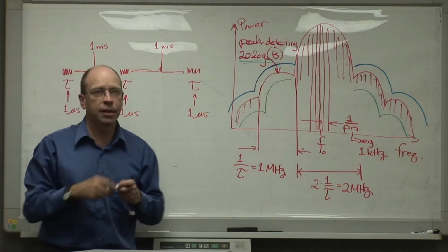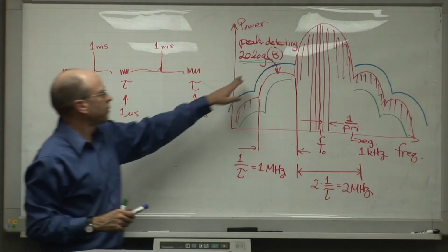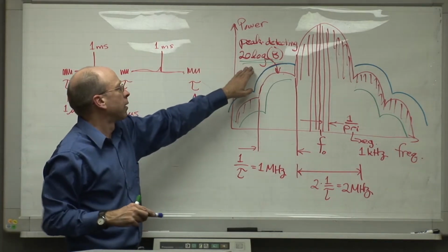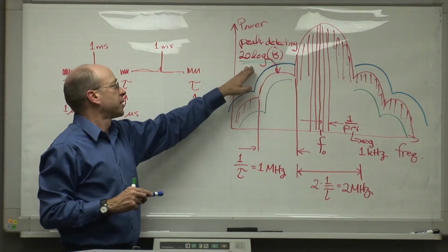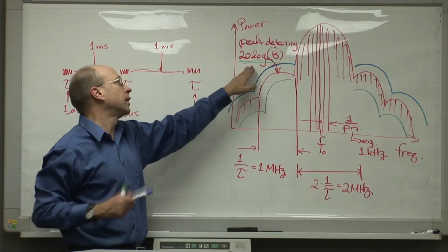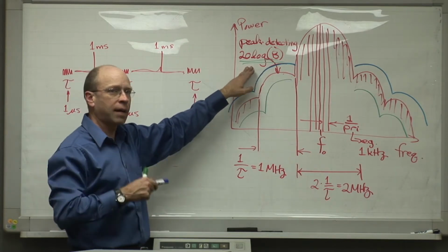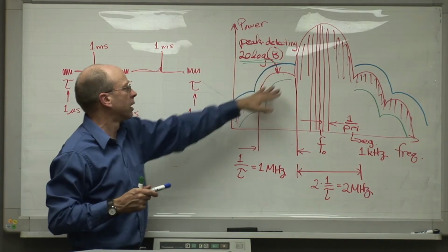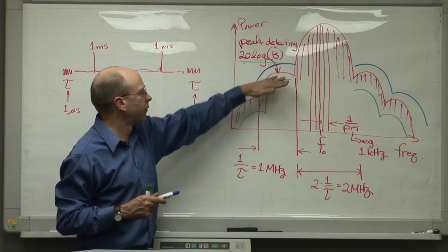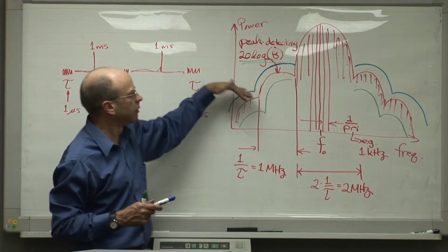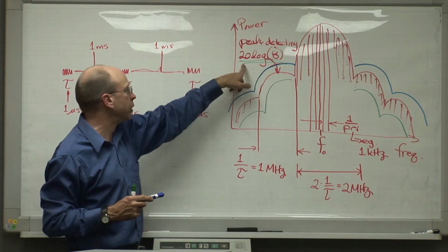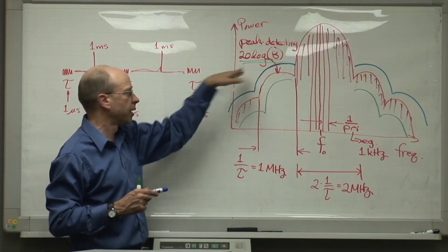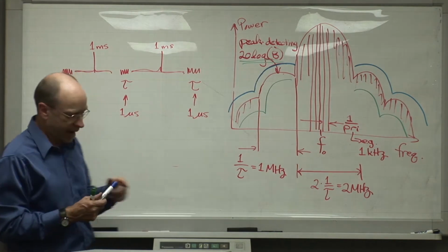Now, I've done studies on this. We've published the studies. Sometimes you see about a 13 or 14 log variation. Sometimes you see a 16 log variation, you might see 20, but it's on the order of 20 log. The exact behavior depends upon the exact shape of the radar spectrum out here. If this spectrum were perfectly flat and had no lobe characteristic at all, we should get an exact 20 log, but the spectrum does vary up and down. Now, however,